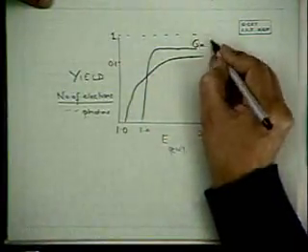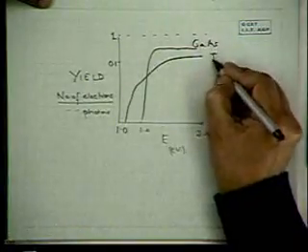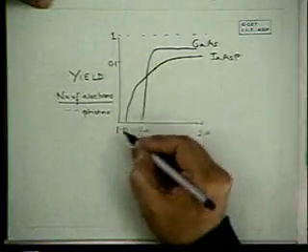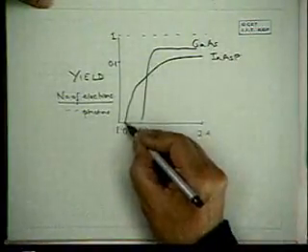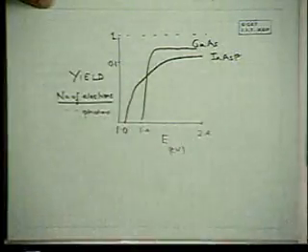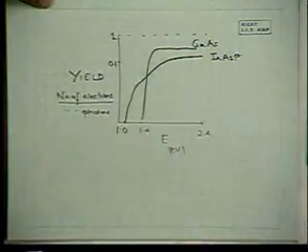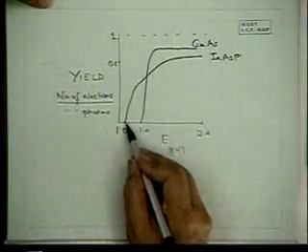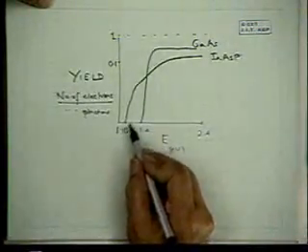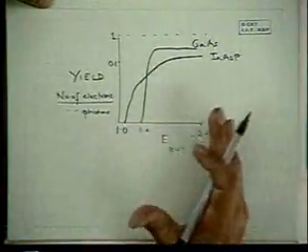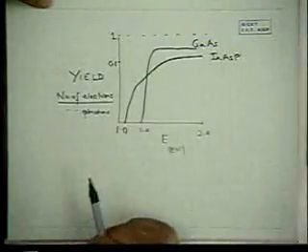This is gallium arsenide. This is indium arsenide phosphide, negative electron affinity. So 1.1 eV corresponds to 1.1 microns. So we have now photoemitters. These are negative electron affinity photoemitters, which have reasonable yield at about 0.9 or 1 micron.